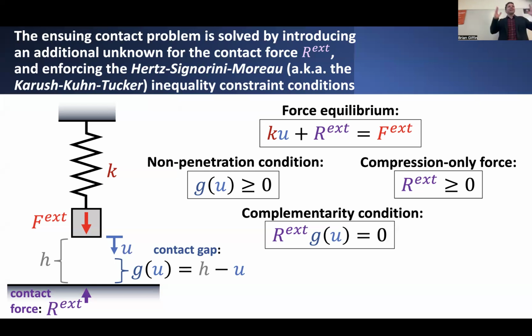Just hypothetically, what would happen if this reaction force were negative? Well, in that scenario, using the sign convention for positive being aligned with this particular orientation as I've drawn it here, if it were negative, it would imply that this reaction force is pointing down, which would indicate that this force is applying some kind of tensile resisting force that would resist the block separating from the surface if it were originally in contact and if somehow we removed the weight and the block wanted to move up.